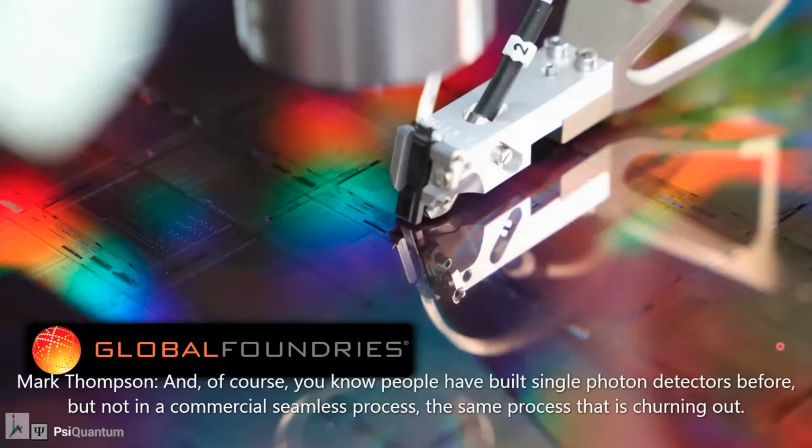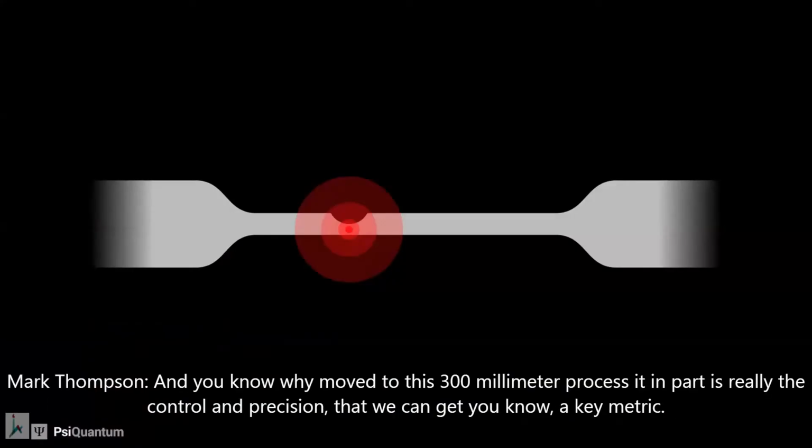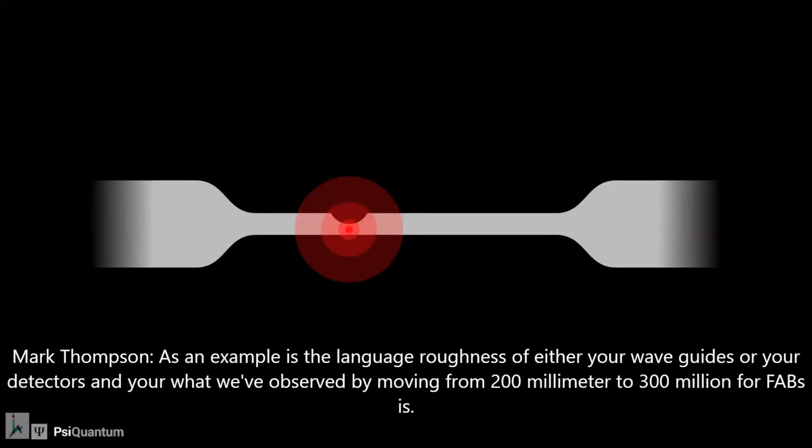And of course, people have built single photon detectors before, but not in a commercial CMOS process, the same process that is churning out millions of chips for cell phones and laptops and so on and so forth. And why move to this 300mm process? In part, it's really the control and precision that we can get. A key metric, as an example, is the line edge roughness of either your waveguides or your detectors.